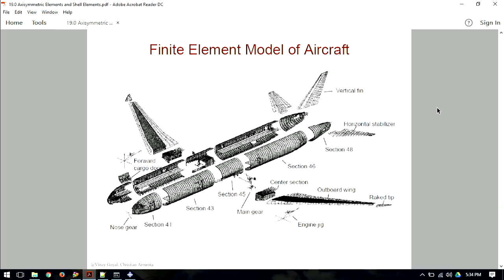We can have our own wing standalone models. And there's some clever ways of decoupling a structure based on how you join it together, so that any load inside the fuselage stays in the fuselage and doesn't transfer to the wing or vice versa. I've dealt mainly with the wing, but I know enough about the fuselage and these horizontal stabilizers and vertical fins. These are basically wings, just at a different orientation.